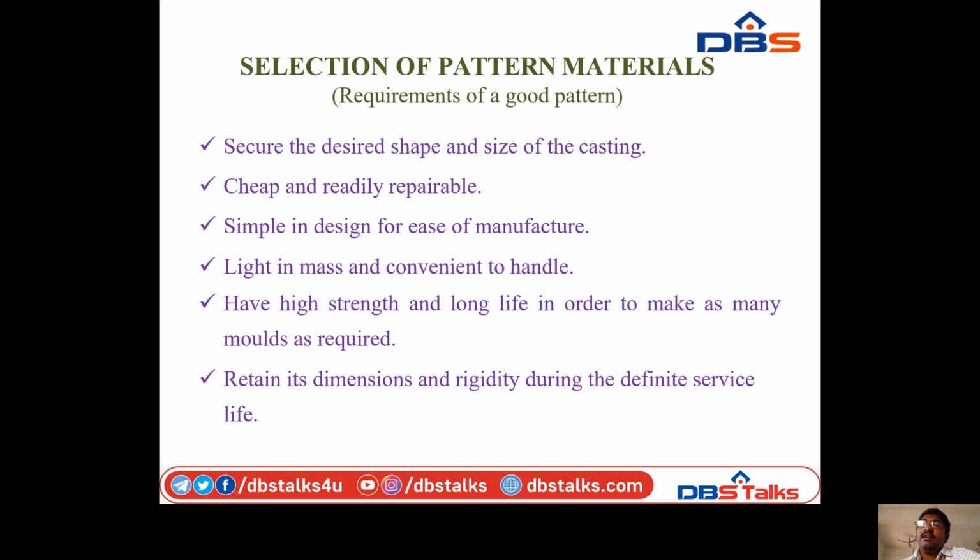Next, last and final, selection of pattern materials. We require a good pattern. It should secure the desired shape and size of the casting. It should be cheap, reliable, and readily repairable. Simple in design for ease of manufacturing.